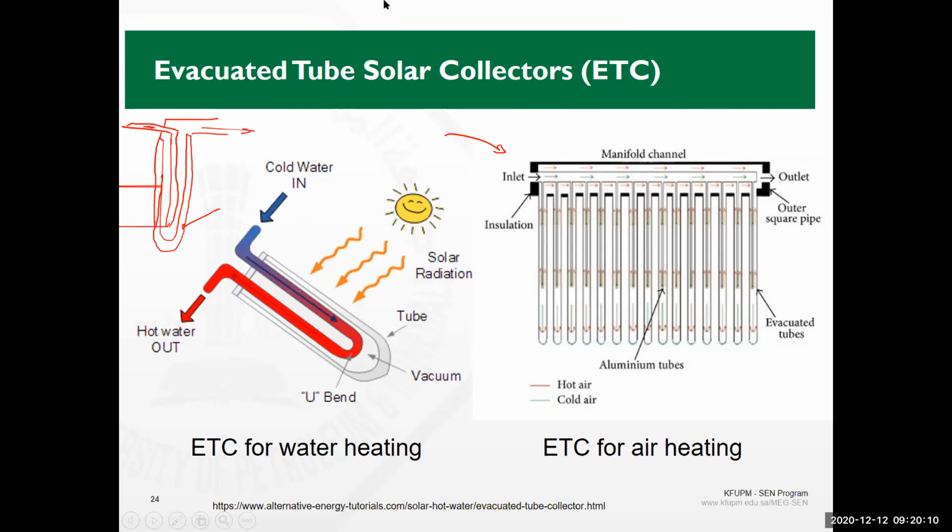If you recall the equation for Q, the heat transfer rate, which is given as m dot Cp delta T, and Q here, if we are talking about solar energy in the order of 800 watts per meter square, you can calculate how much is the area. The smaller the m dot, the bigger the delta T. So having lower flow rate is going to make sure that it leaves at higher temperature.